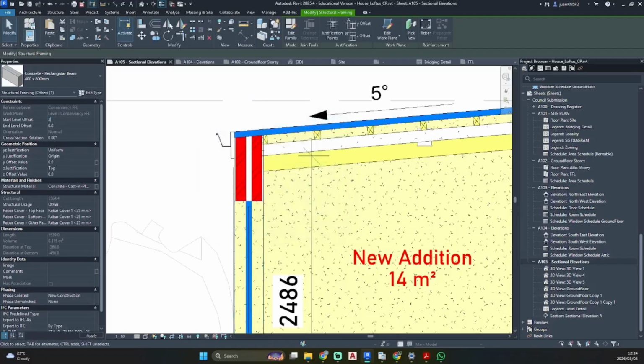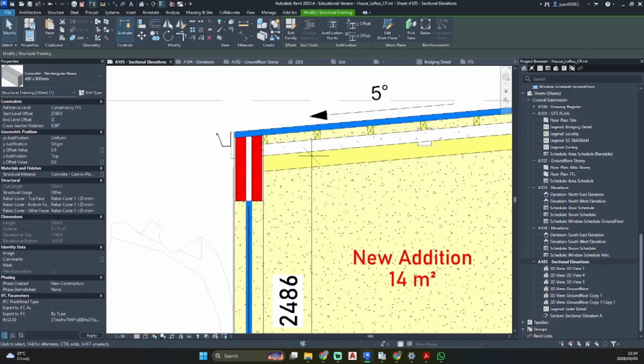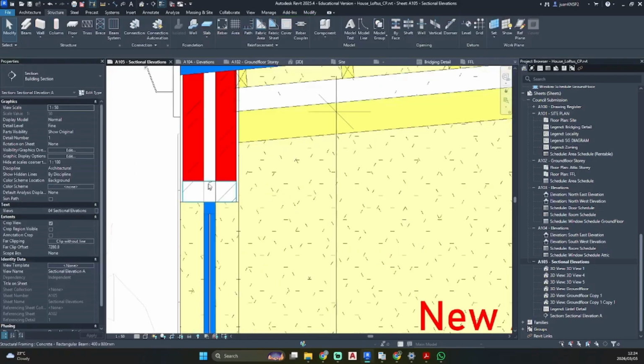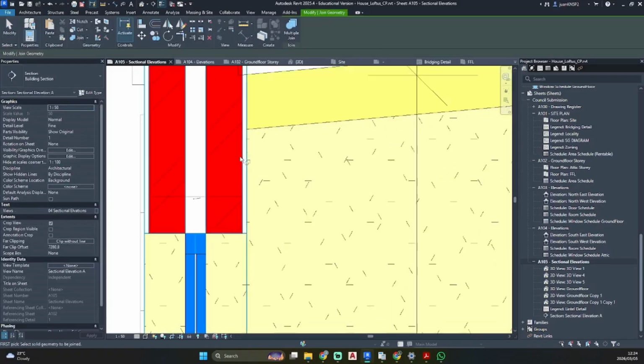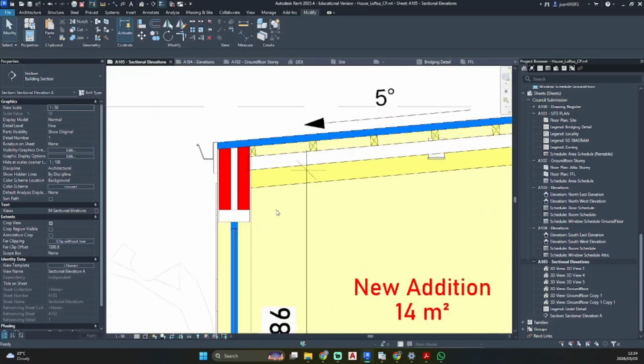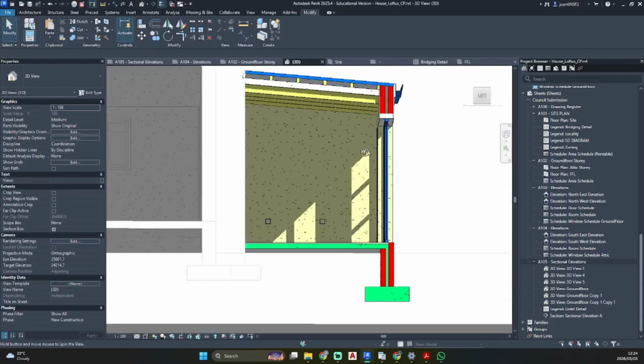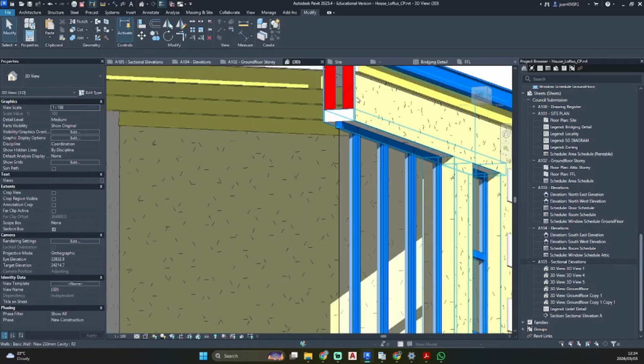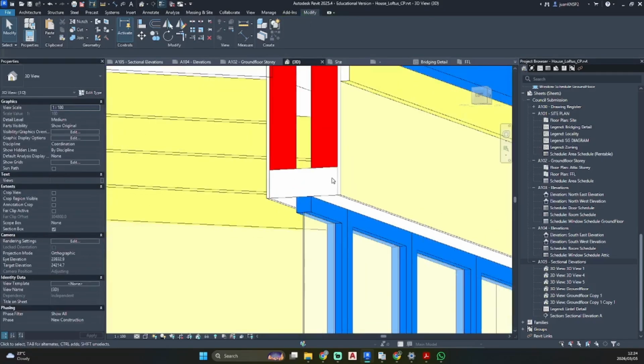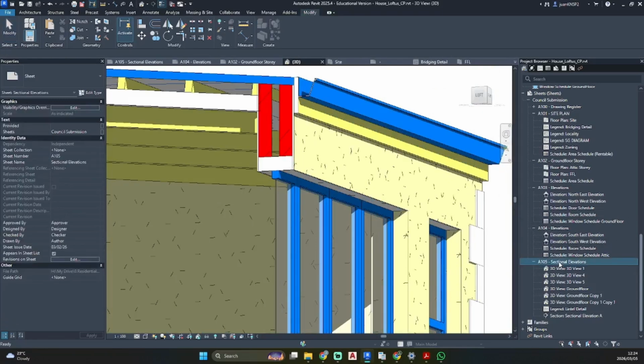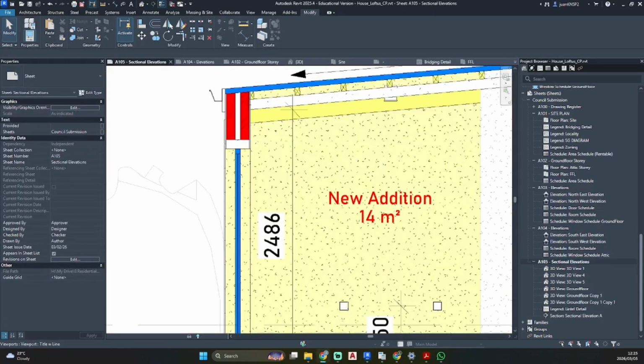And we're going to give you an offset of 2.1, 2.1. There we go. And we're going to use your bottom so that you flip up. So just to double check this, let's go and cut our wall. Okay, so you need to maybe join it. There we go. Now we have that in our lintel, but we still have the plaster going over the lintel. So I'm going to go back to my section and let's just check.